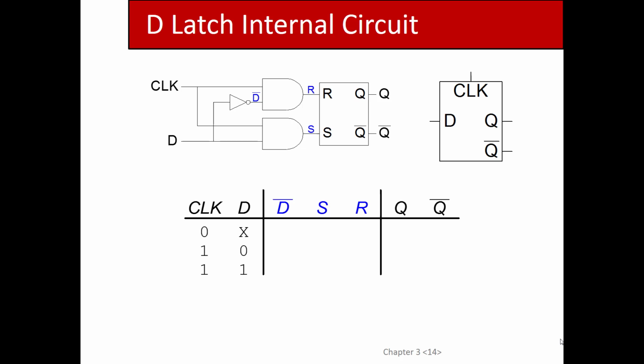What do you mean by you saying you capture it? So it's like I give it a D. As a user of this system, I will provide a D input. Now I can change that D to 0 or 1, and when I change D, Q will also match. D is my input, Q is my output, so if D is 1, Q is 1, D is 0, Q is 0, but that's only while clock is high.